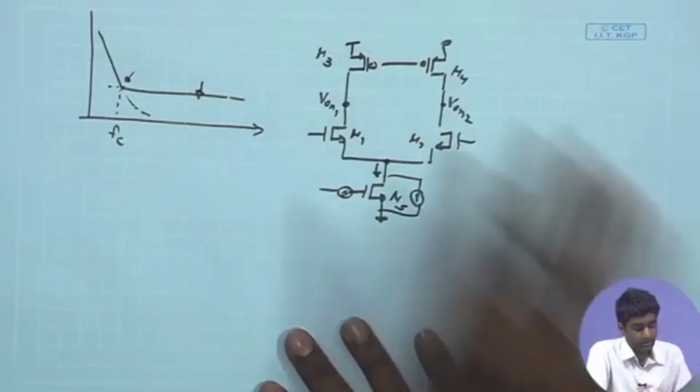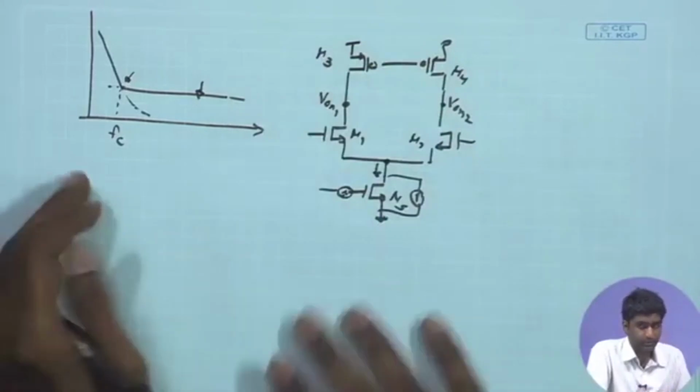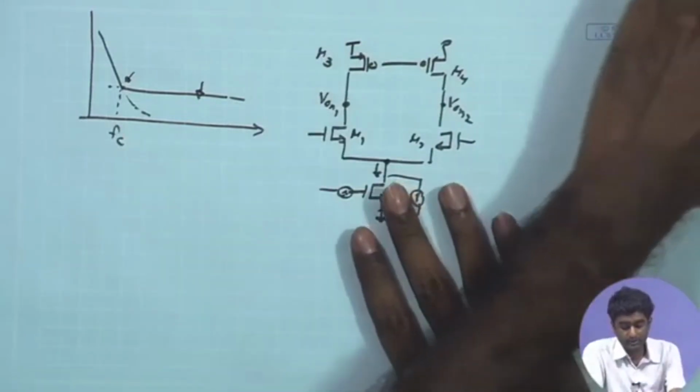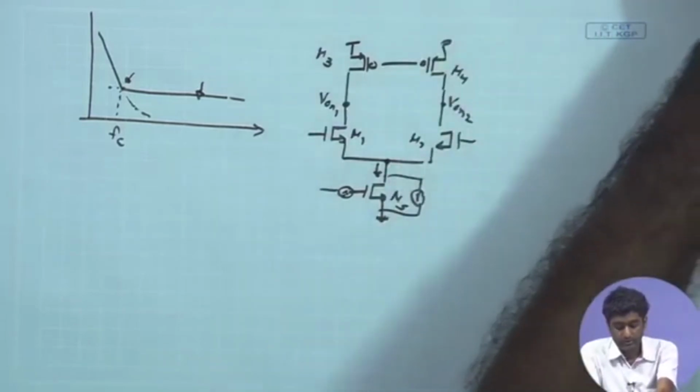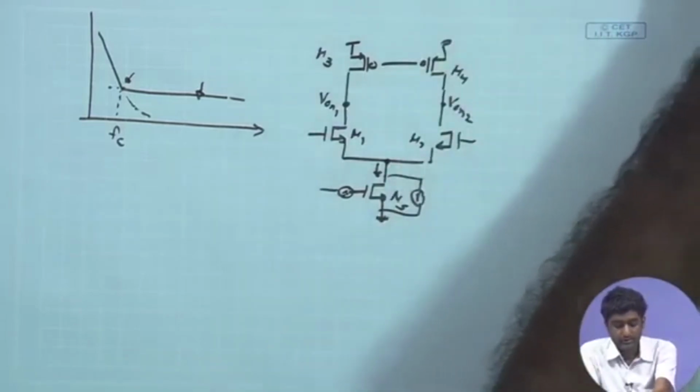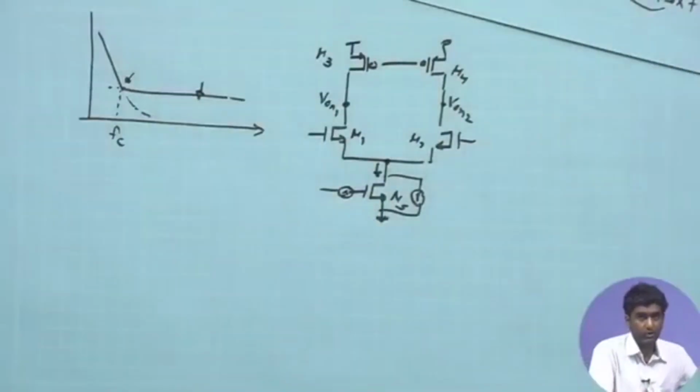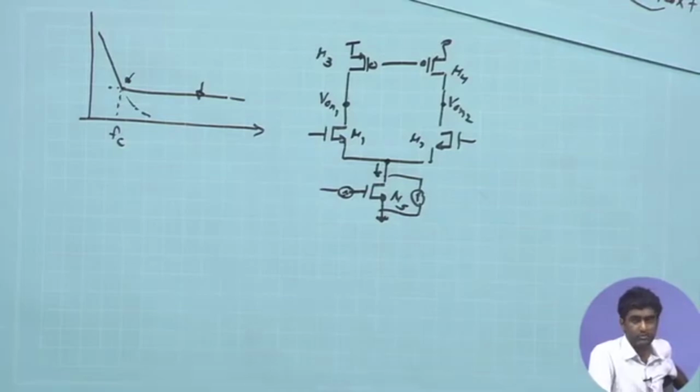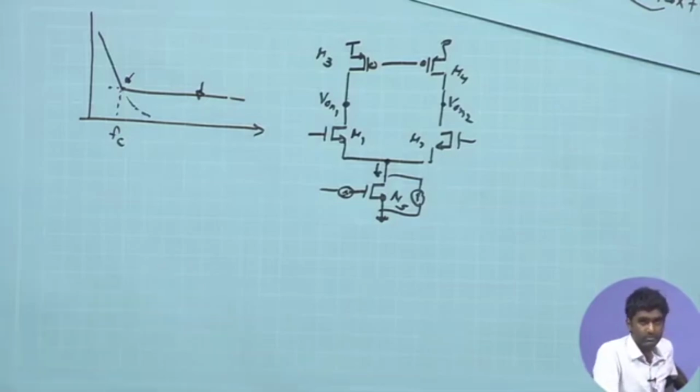Now, if we look at the minimization of FC, if we revert back to our expression and try to see what it takes to minimize FC in order to cater to our low frequency signal. Remember, we are talking about signal content which is going all the way to 0.5 hertz, and we need to pass up to 0.5 hertz of signal, and our higher cutoff frequency for the high pass response also that we designed with the help of that feedback resistor RF for input DC biasing, that was also supposed to pass that 0.5 hertz.